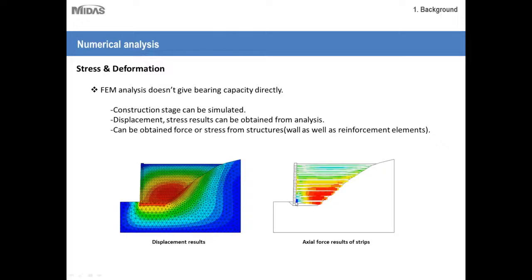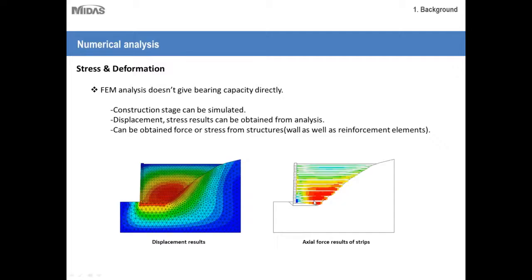This is because we started erecting the structure from bottom to the top. So as and when we started putting in the backfill, the lower part of the structure would start deforming, and that is why we have the retention system or reinforcements. So they will hold it in its place. So that leads to excess or higher axial force in the bottom part.